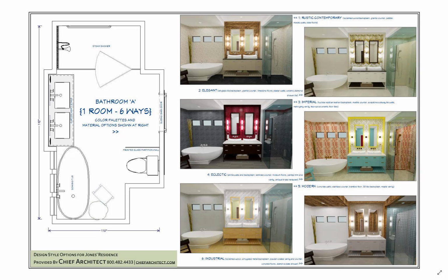Today I want to talk about setting up custom materials for Chief Architect. You can see on my screen I have this bathroom and it's been decorated in 6 different styles. So all I did was go online and I found my favorite brands and I did screen captures of those tiles and I converted those to materials that could be used in painting my scene in Chief Architect. So let's go over how that's done.